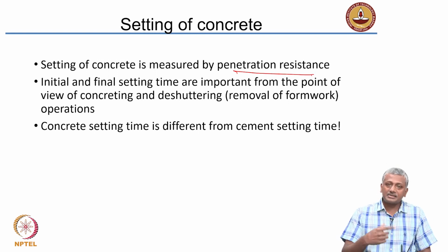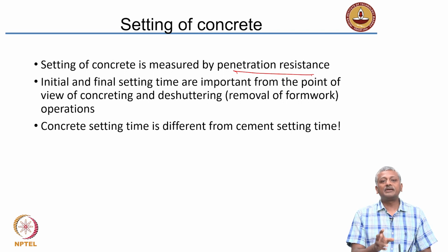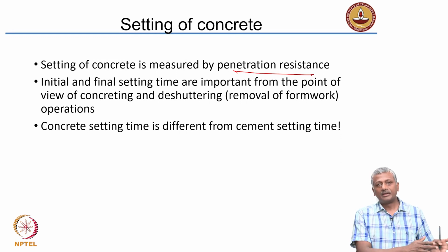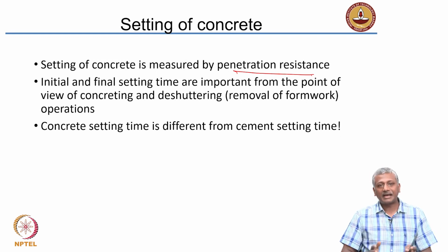Again, just to emphasize once more, concrete setting time may be quite different from cement setting time. This is again an issue because concrete setting is also determined by the cement paste to aggregate ratio. It's also determined by the presence of these mineral and chemical admixtures that we add to the concrete. When we look at cement setting time, we don't add any of those ingredients. Okay, we test cement setting time as it is, whereas for concrete we test it as the concrete mixture has been prepared with all the additives. So, because of that, you need to ensure that you have some sort of an idea about how long it takes for concrete to set.